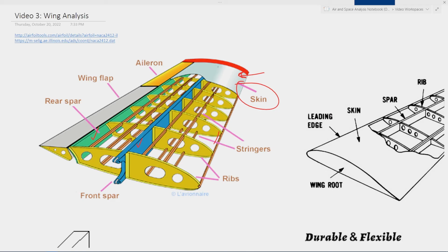and stiffens the entire structure. And that also makes sense because if we're bending around a neutral axis of our wing here, we can see that the skin itself is metal that is fairly far from the axis that we're bending around. So it does add some stiffness to the wing. So that's why our skin is kind of twofold.